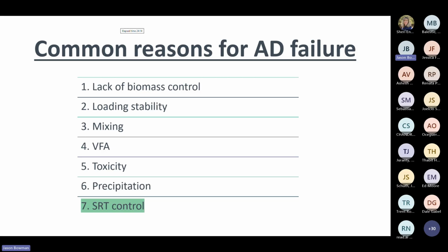However, traditional digesters lack this control. Going back to that in equals out equation, 1 gallon in is 1 gallon out. There's really no recirculation going on in these systems. So this is also why traditional digesters require excessive storage time.